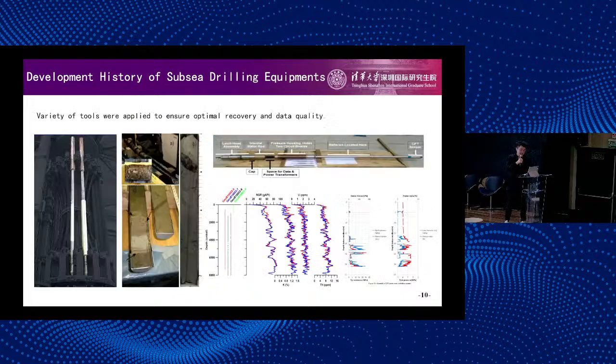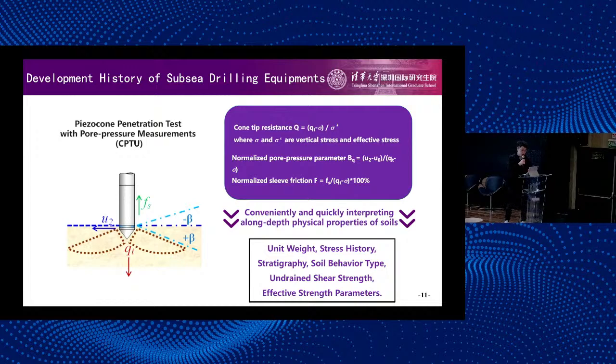Again, compared with second-generation drills, the third-generation drills now incorporate various in situ testing tools such as logging and CPT tools aimed at achieving multifunctionality while providing more precise geological information. It should be noticed that CPT technology plays a crucial role here. This is a cone with several sensors fixed on a pushing rod, and while the cone penetrates into the strata, the sensors collect signals and transmit data to the logger in real time along depths.